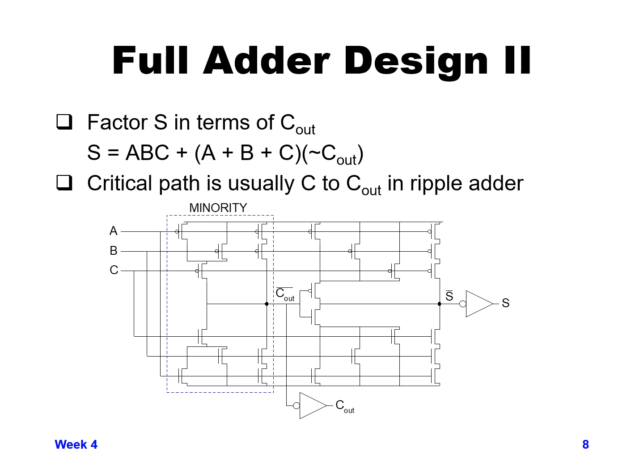And the other factor in here, so the sum might take a little bit longer, but generally the sum is not the critical path because it doesn't have to go to the next order bit. So we want the carry out as quick as possible, and you can see we can get a carry out bar, and then we include an inverter, so we have carry out bar and carry out that can be used going into the next stage if we need a carry out bar into the next stage.